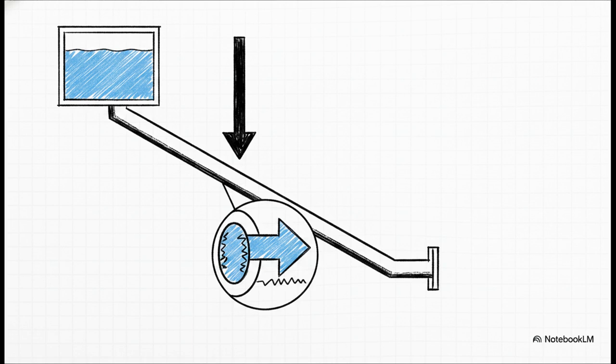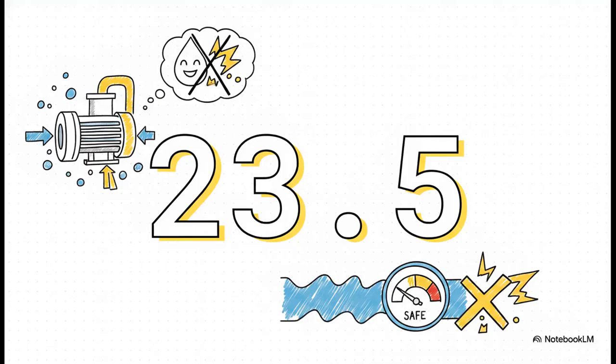And based on our Reynolds number, we get a pipe friction factor of 0.0306. When we take all of those specific test variables, plug them into our NPSH equation, and subtract the vapor pressure of 25-degree water, crunching those numbers gives us an available NPSH of 7.148 meters, which is roughly 23.5 feet.